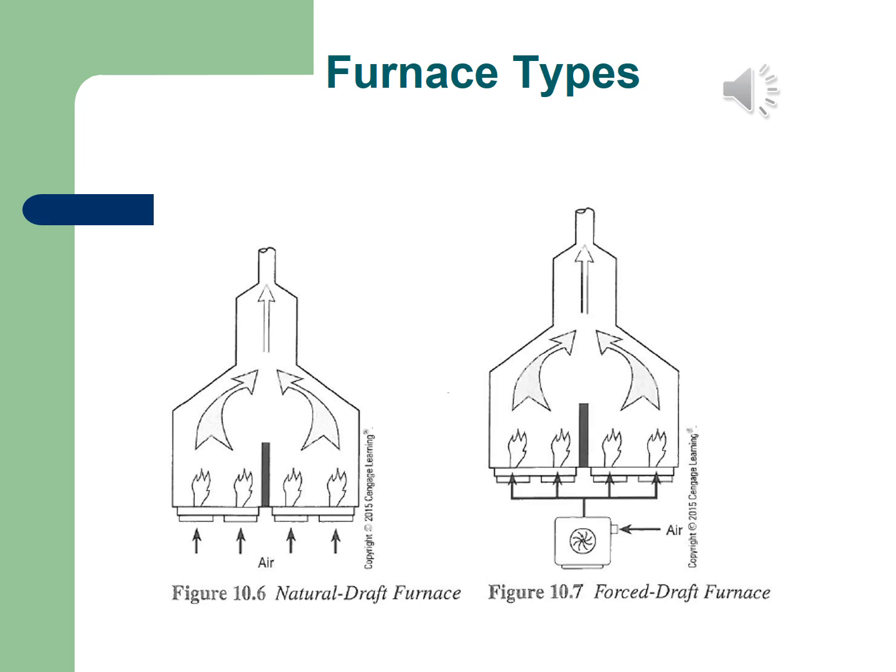Then you also get a forced draft furnace. Now usually if a fan is placed at the bottom or at the starting point of, say for instance, that furnace, you will call it a forced draft fan. So it forces the air through the furnace. So with this, there is a fan connected at the bottom, and this is just to enhance the flow of the air through that specific furnace. So it's again important. We'll see on the next slide, you also get induced draft fan.